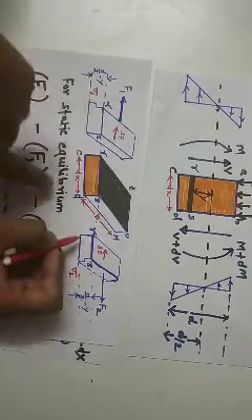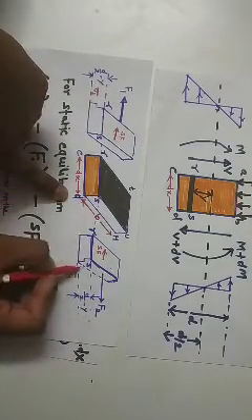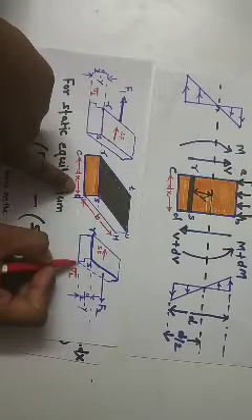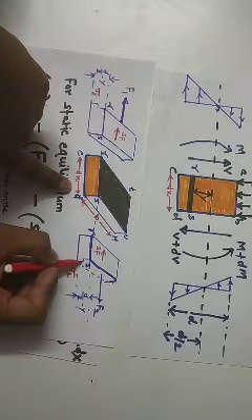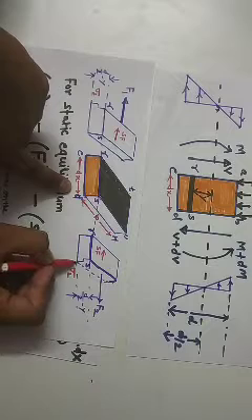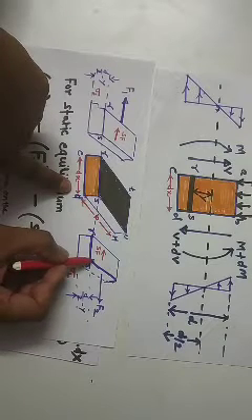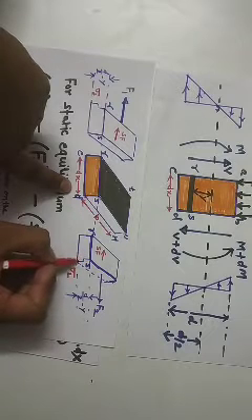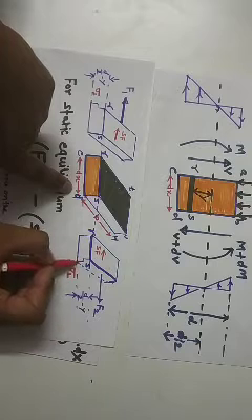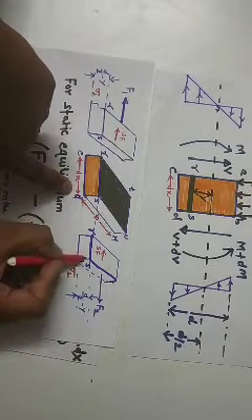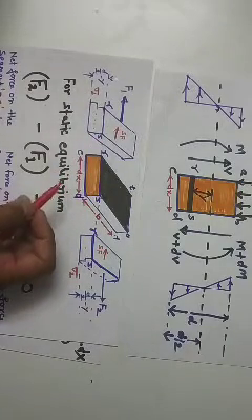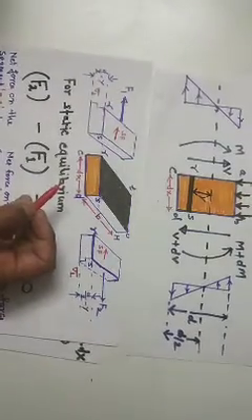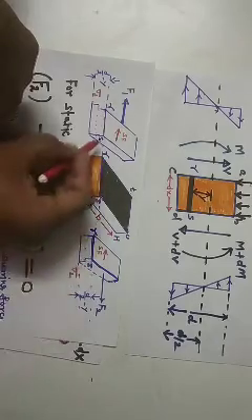Clear? Similarly, due to this sigma 2, the bending stress set up by M plus dM, the layer close to D has higher extension in comparison to the layer away from it. Clear? And we know why it is higher: because the bending stress is maximum at the top, and when we move from the topmost layer to the neutral axis, it starts decreasing, right? If it is decreasing, that means there is sliding of layers. This layer is sliding over this layer, and similarly this layer over this layer. Due to the sliding of these layers, shear stress is set up in the beam along this layer RS.